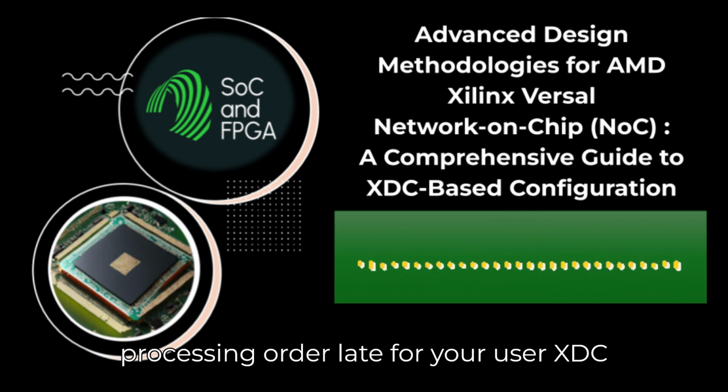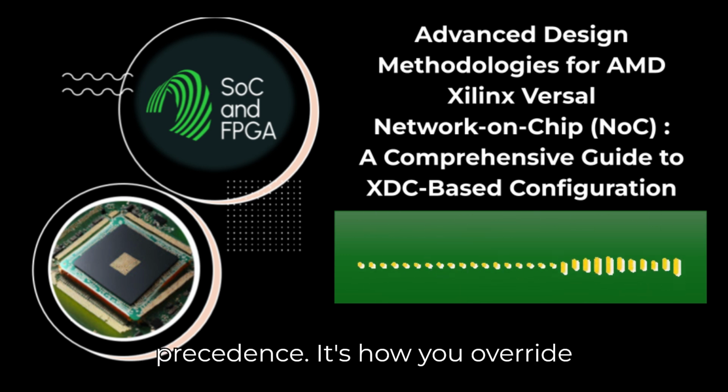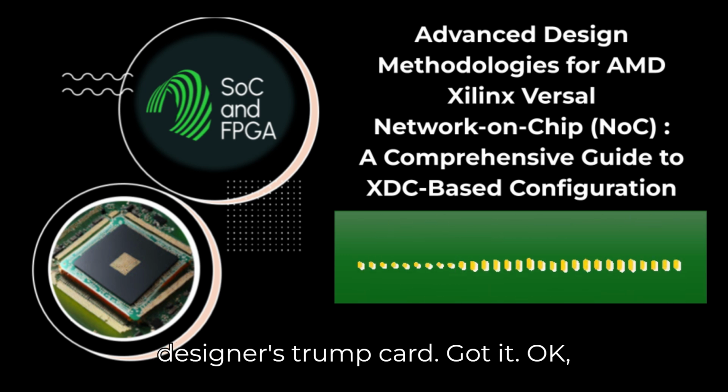If you set it to processing order late for your user XDC file, you're basically telling the tools, my instructions come last and they take precedence. It's how you override defaults for those critical things. The designer's trump card. Got it.